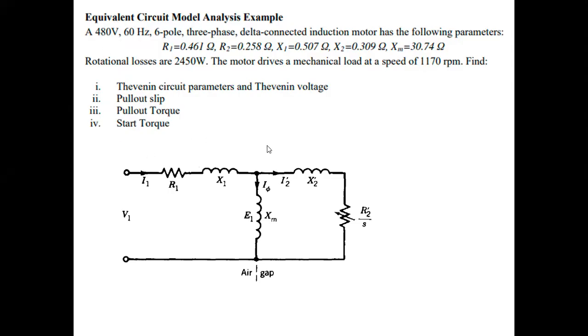So first of all, if we recall, we said that for purposes of deriving the torque relations, it was easier to Thevenize the starter side of the circuit. So we viewed the starter from this point of view, and we Thevenized this circuit. If you recall Thevenin's theorem, when we are Thevenizing, we get the voltage as will be viewed from this point, and that will be the open circuit voltage. And then if you look at the impedances, it seemingly looks that XM is parallel to the impedance of the starter. So that's what we do in our solution.